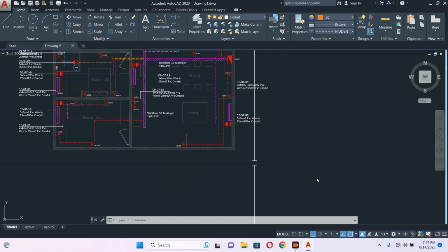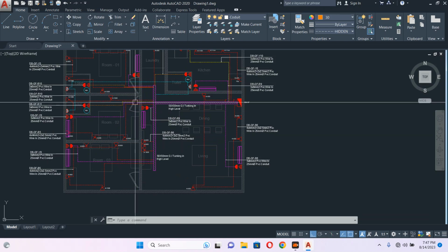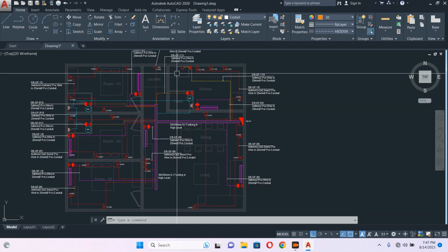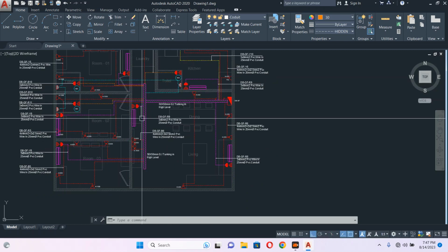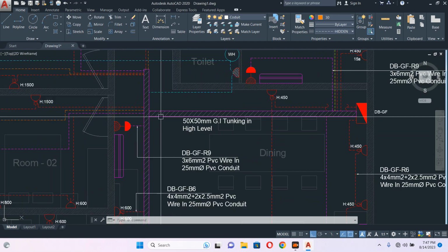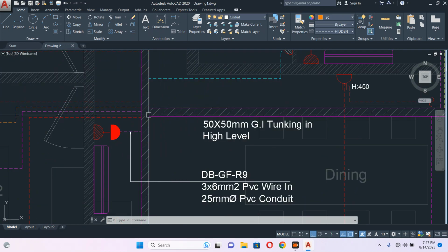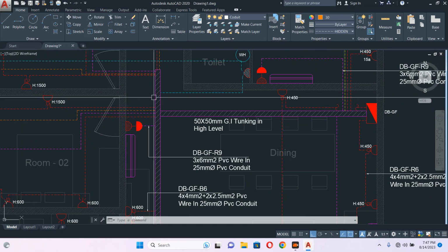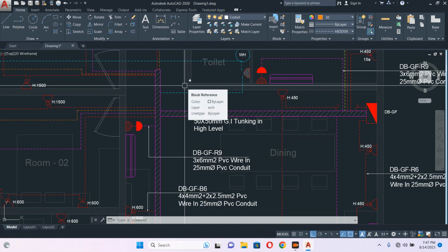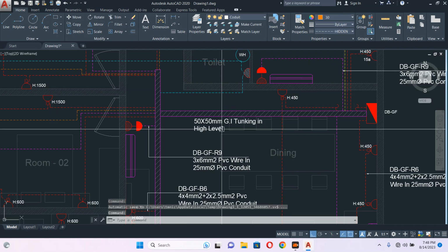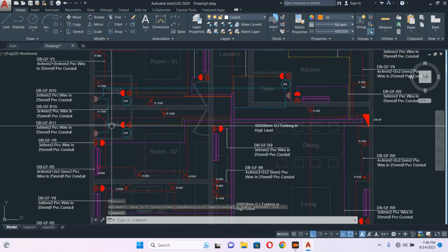It's almost one hour now. If I take more time, it will give you a headache. In my next video I will give a wider explanation, because now just try to understand the small explanation. This trunking should not be like this, it should be perfect, with T connections and everything. The trunking also has a containing factor, and the cable also has a factor. So there is a calculation with the trunking factor and the wire factor to check whether it is enough or not. I will teach you that much later, but keep it in your mind, there is an option like that.